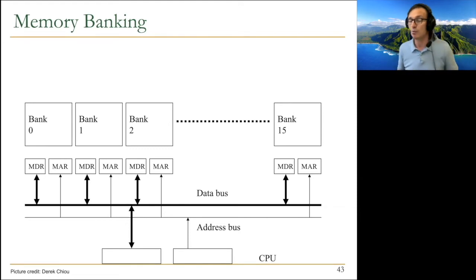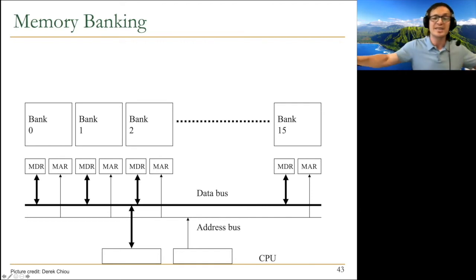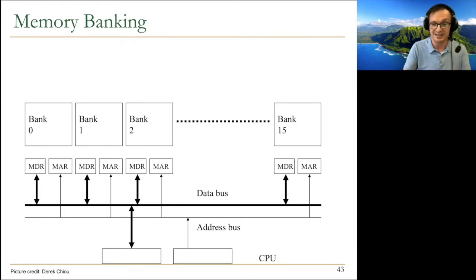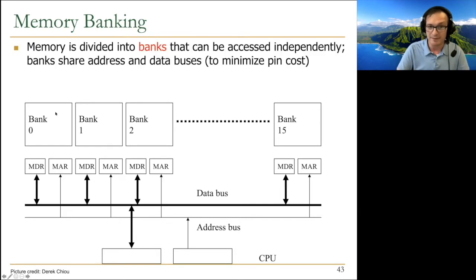You sustain one element per cycle throughput, even though your memory access latency, bank access latency, is more than 1, but you have enough banks so that you never have a gap in your throughput. Basically, you always get one access per cycle. Now, of course, this requires your data mapping to be nice. If your stride is 1 and consecutive words are mapped to consecutive locations, that's great. Okay, we're going to get back to this.